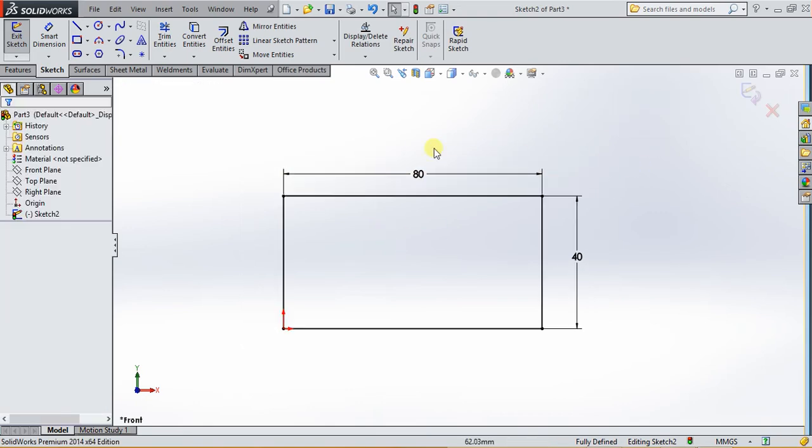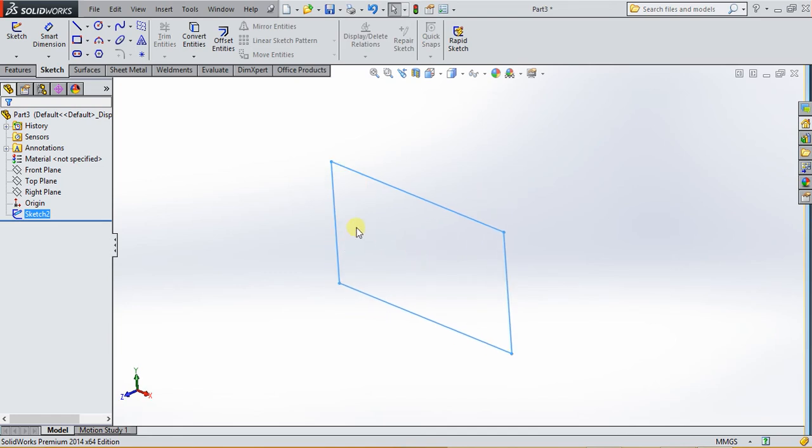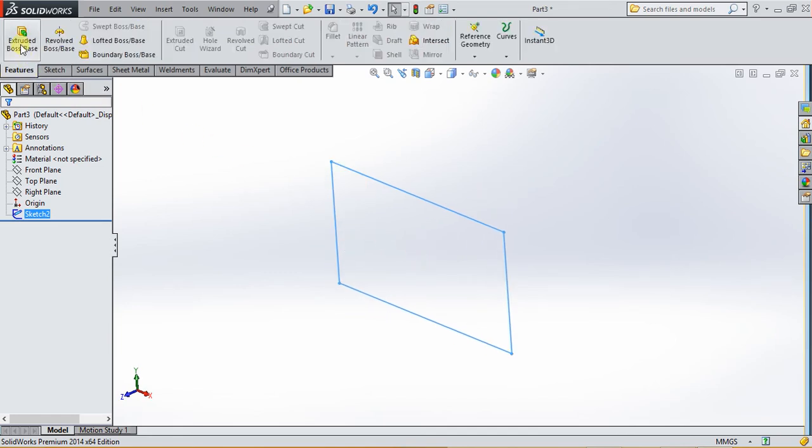Now this is what is required whenever you complete your sketch in SolidWorks. Make sure that the entire sketch is completely black. Once you are finished making the drawing, then I will exit from the Sketcher Workbench by selecting this icon. I will assign a 3D feature, say Extrude. So to assign it, I will go to Feature, select this Extrude.